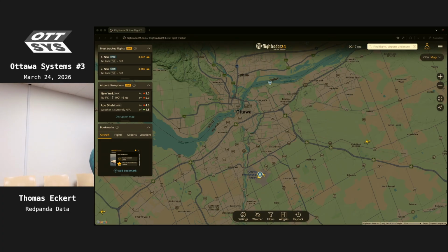Does anyone have an idea of why I want to shorten my antenna for ADSB? Why would a shorter antenna work better? Higher frequency. Yeah, but then what? Like I could receive ADSB here. Why would it be not as good? Something about trying to catch resonance.